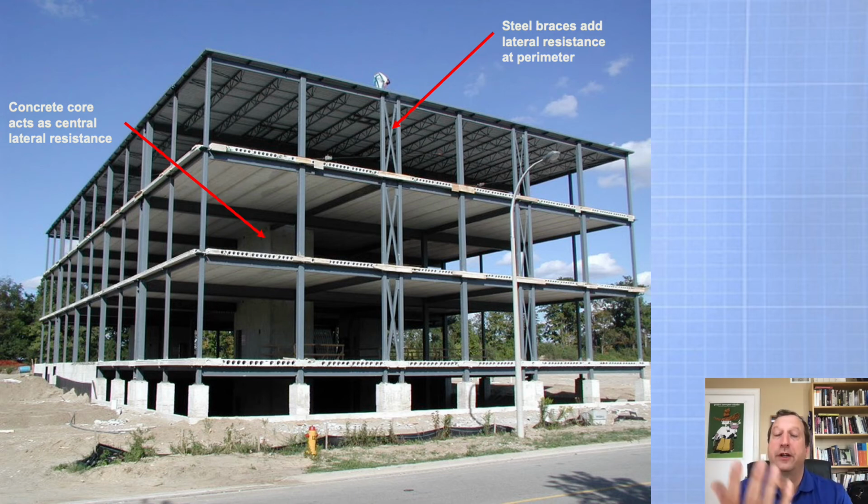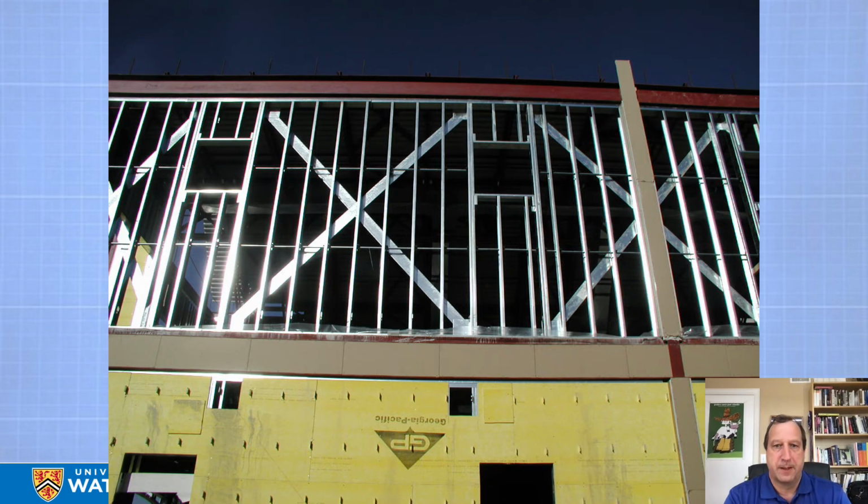That's enclosed in a concrete masonry exterior, which is both fire and sound resistance, and it could be deployed to resist lateral loads. But rather than enhance the strength of that core to take the loads of this whole building, they integrated these braced frames that they could pre-assemble. So this is a common economical solution.